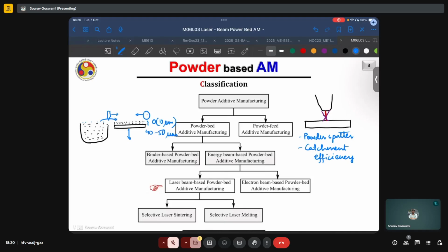Clearly, we see that here the powder particles do not really have any inertia of motion associated with them. Whereas in the previous case, the powders were reaching the system with certain momentum. The powders only have motion at the start of the layer, while they're still being shifted into the printing region and compacted into a single layer.